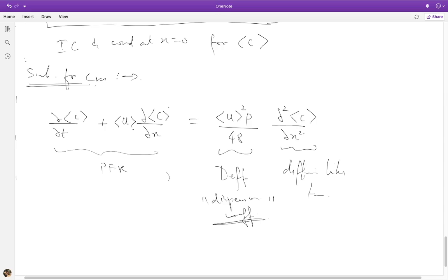So you see now that what I really have looks like an advection diffusion equation, but whereas earlier I had diffusion in the radial direction and advection in the x direction, when I have now obtained this effective equation for only the cross-section average, which only depends on x and time, I have a diffusion advection equation, but where advection and diffusion are in x.